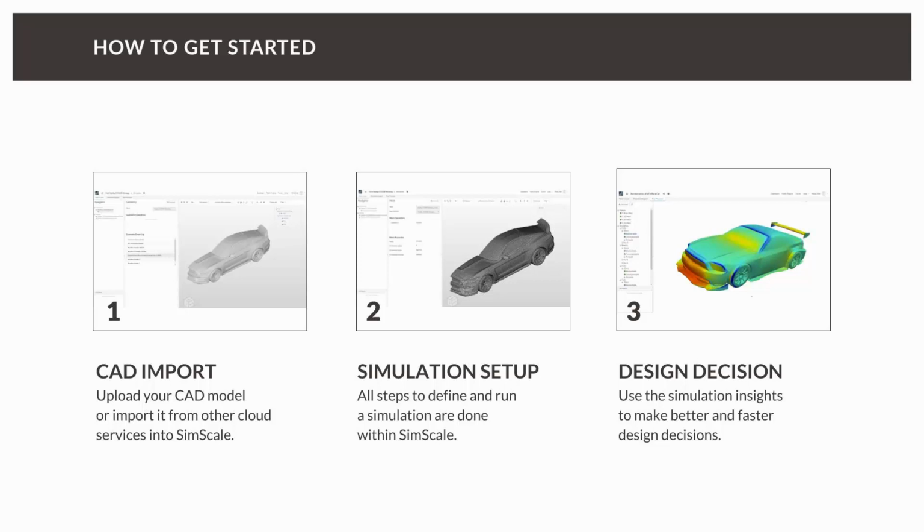For a CFD simulation, you need a CAD model of the car you want to simulate. SimScale has some minor CAD functionalities to clean up a model, but we really recommend preparing your model in your CAD system, since you will have the most control over your models there. If you want to run a simulation of your CAD model, you need to make sure that the model is watertight and closed.